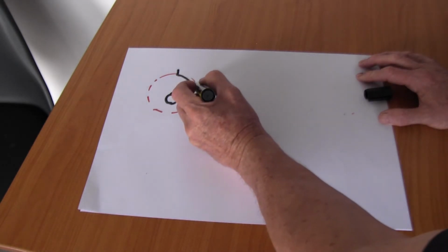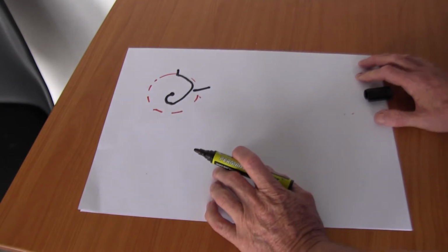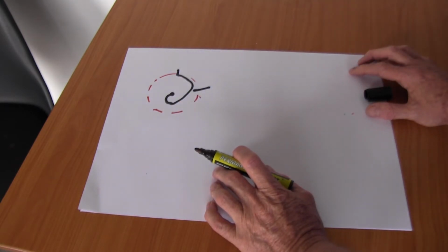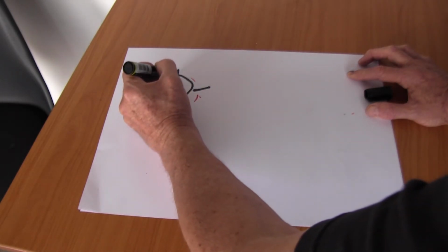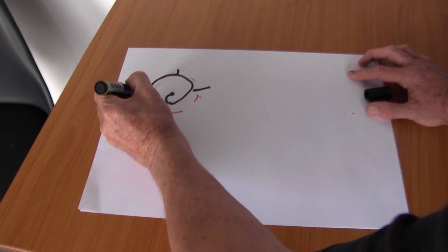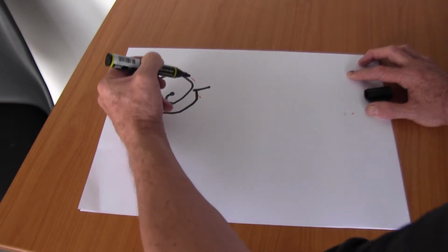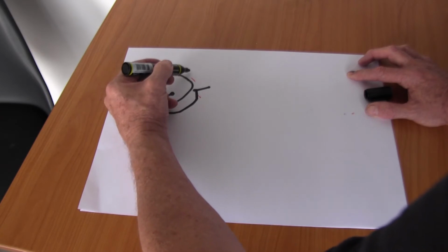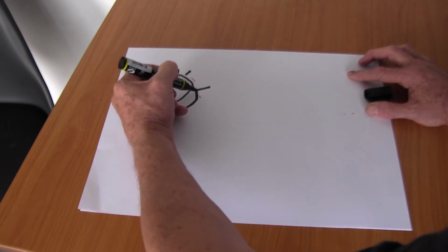So the next thing is that from our database we know for this specific hole on this specific material using this specific cut chart that we're going to cut this hole at what we're going to call speed 1 all around here to this point here, and then we're going to turn the torch off before we get to 12 o'clock.